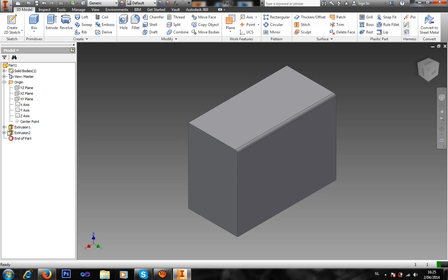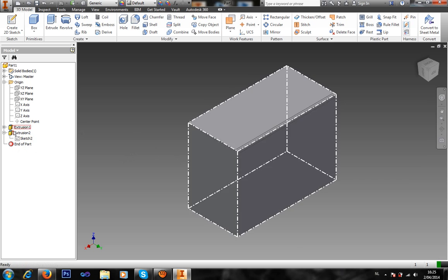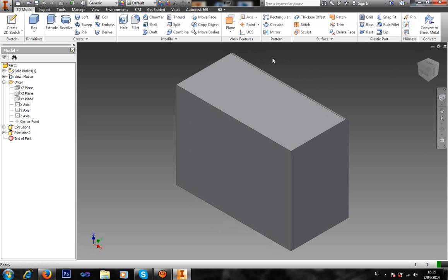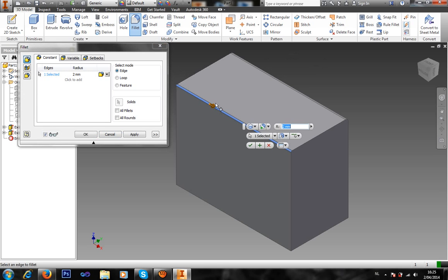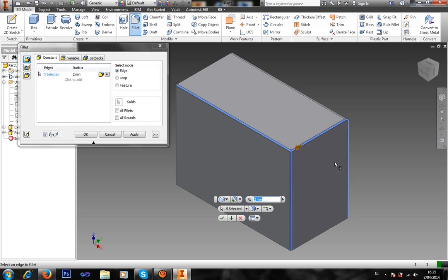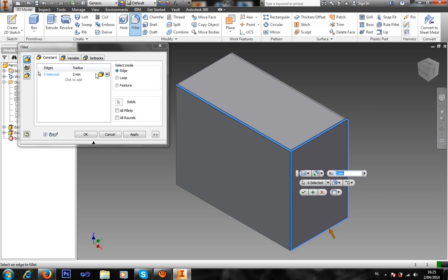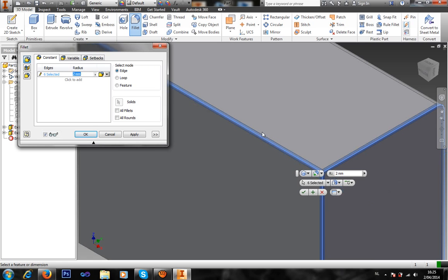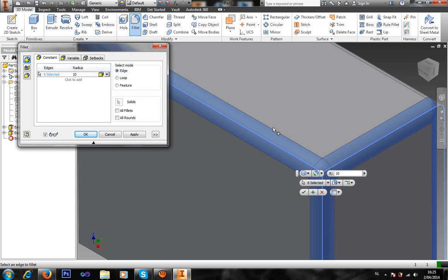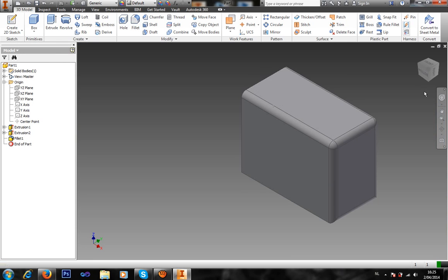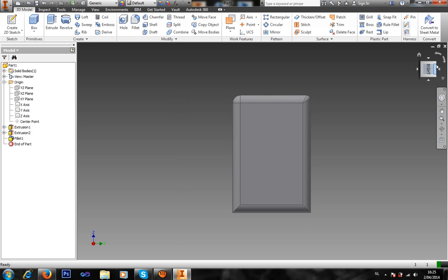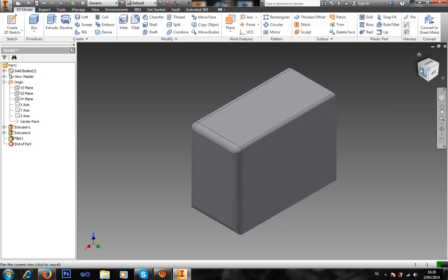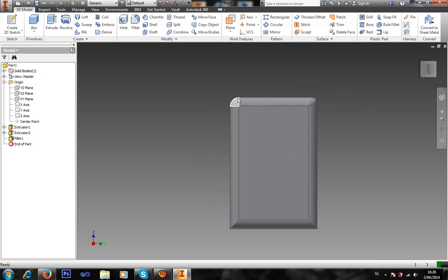You can do it, like I said, by creating a sketch, doing extrusion and all that, but you can do it way easier by picking the fillet function. Basically what it does is exactly the same, only you click the sides you want to round. Let's say all of these. You type in the radius, which means how round the edge would be, and pick 10 again, and press OK, and there we go. We got all the edges smoothed out, except for this one, because we extruded it, so it doesn't recognize it correctly. But basically it's all smooth now.